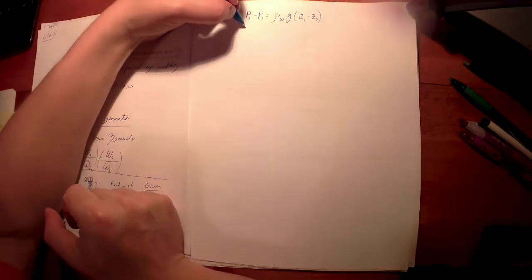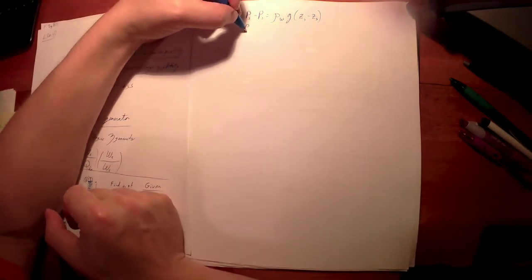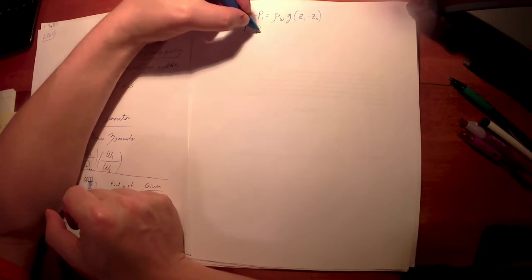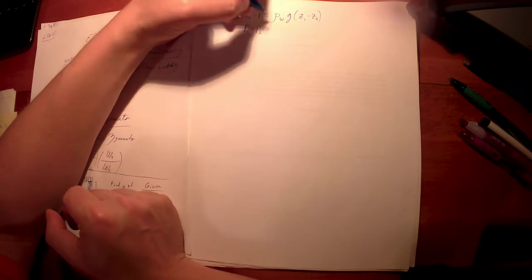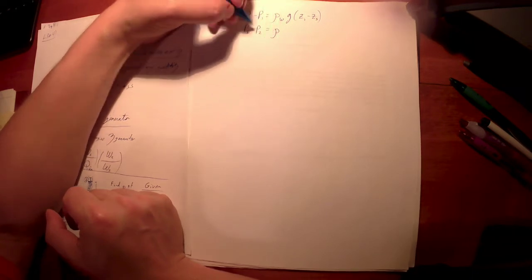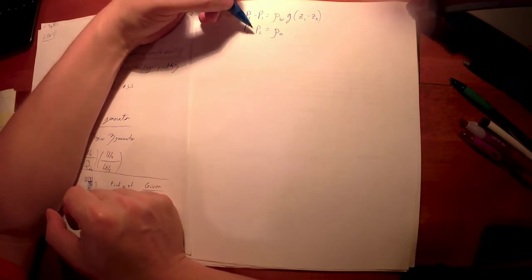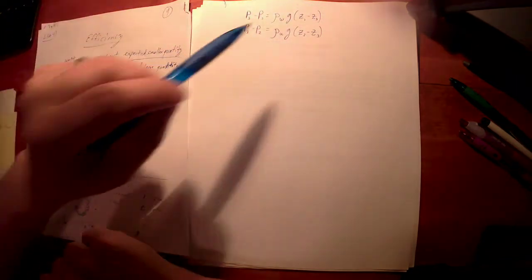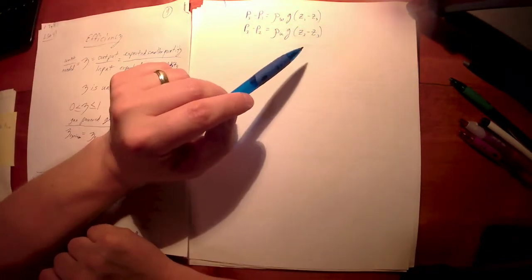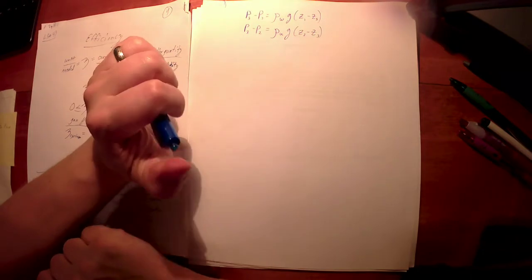Now, I've got this unknown fluid between 2 and 3, so I could say P3 minus P2, and I could write that in either order, by the way. I could say P2 minus P3 there. It's an unknown fluid between 3 and 2, so I'm going to subscript that density, that rho, with a U. So it's the unknown density times gravity. If this is 3 minus 2, this needs to be 2 minus 3. Again, we've derived this equation where Z represents elevation. So as I increase Z, pressure decreases.